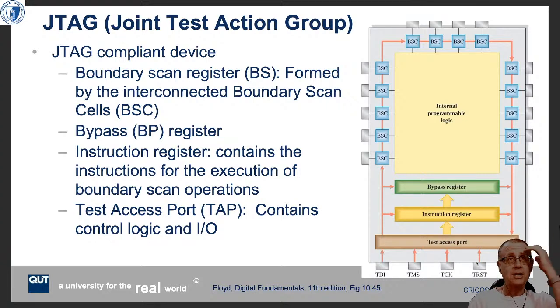Okay, so we're going to be using JTAG. I think I said earlier, this device has two programming modes. It's got the AS, which is the serial programming, and it's got the JTAG. The thing with JTAG is, as soon as you turn off the device and turn it back on again, these BSC numbers have just disappeared, right? They're no longer relevant.